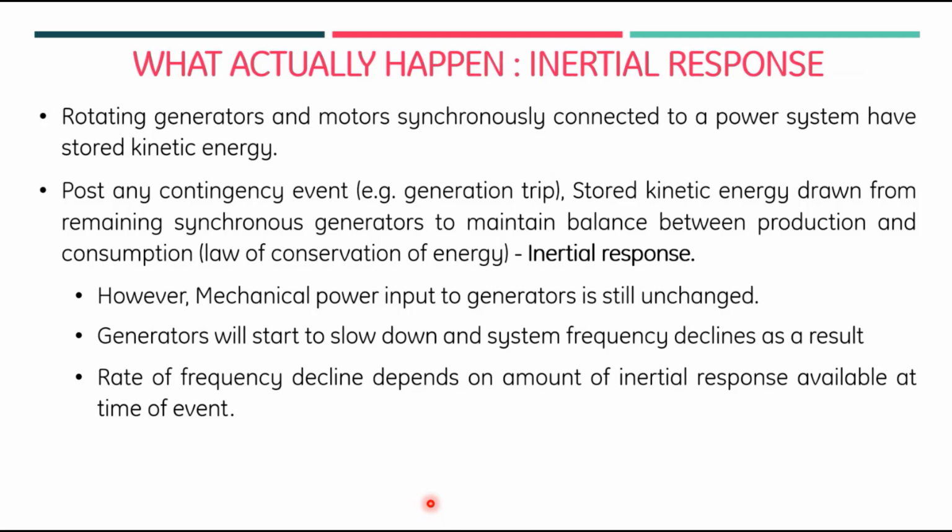And if we talk about any particular generator, how is this kinetic energy stored, and what is the concept of inertia? In simple words, you can explain it like this. If you start any particular generator, first we know what the speed of the generator should be to produce a 50 hertz electrical signal on the other side. From the mechanical side, what should the mechanical speed be to provide the electrical frequency of 50 hertz? The formula is already there. Let us say it is a 1500 RPM machine.